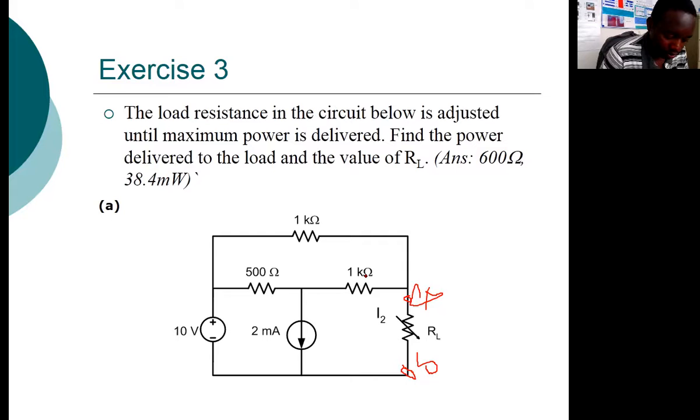These combined, and we have our Thevenin due to the current source, we can say Thevenin C. Now, in that section, you have to see that there is no current flowing to the terminals A and B, because we are dealing with the open circuit voltage. Since we are dealing with the open circuit voltage, our currents will be flowing in different loops.